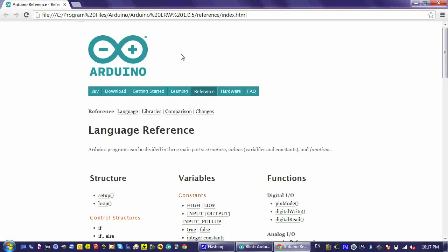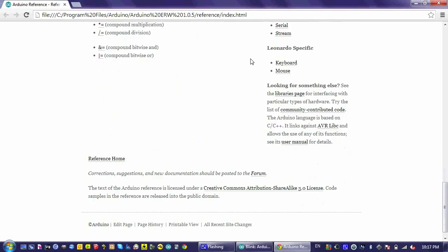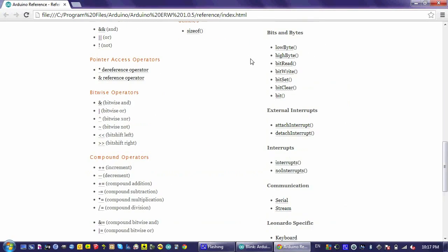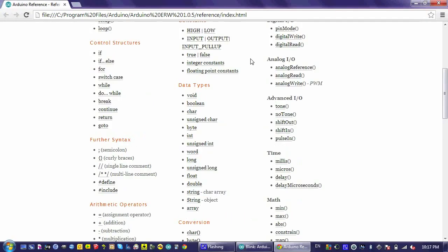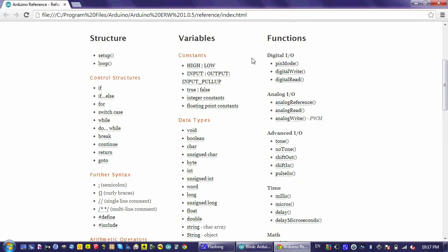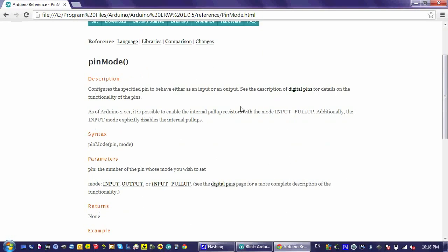I will see information or links to information for a ton of different Arduino related operations, functions, data types, control structures, everything. At the very top I see pinMode, top right. And if I look inside this page, I can see that pinMode has a syntax section that explains how I'm supposed to use it. It tells me what the different modes are.